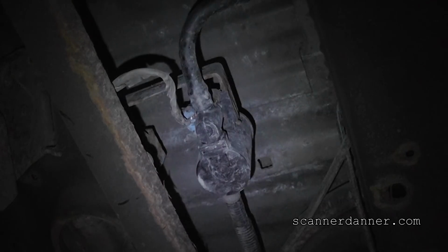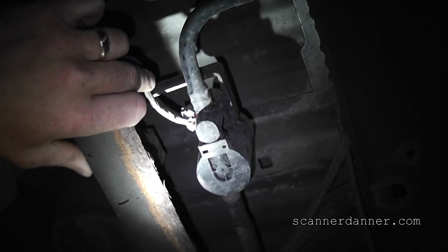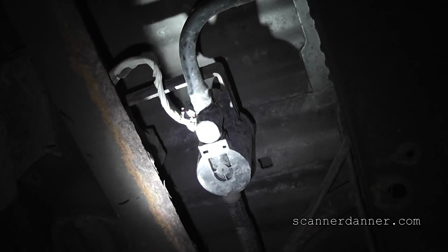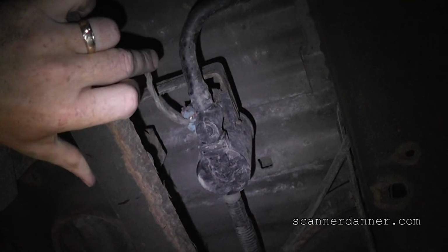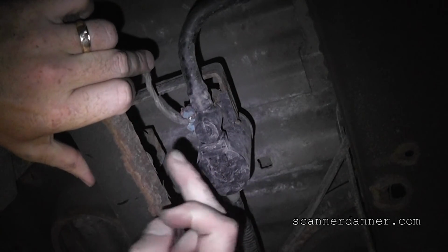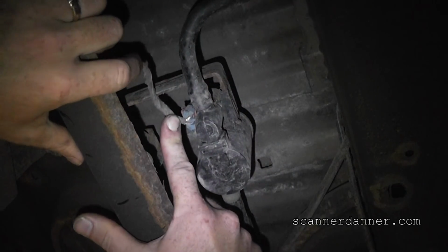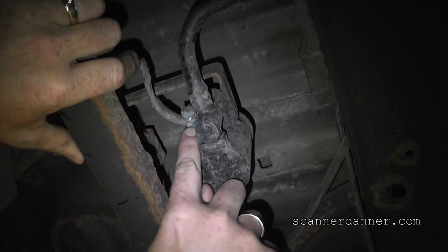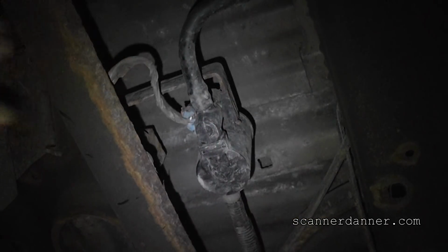Now, looking at this, I don't know how well that's showing up for you guys, but it looks to me like the wiring has some white powder on it, and I know the camera's not picking that up. There were two things I was thinking of. One is pulling the tape off to do a visual inspection on the wiring, which wouldn't be a bad idea. But I can actually get to the wires no problem to back probe them. So I'll just do two voltage measurements and then we'll go from there. The red and white is to the right and the white wire is to the left, so the computer control wire should be on the left.